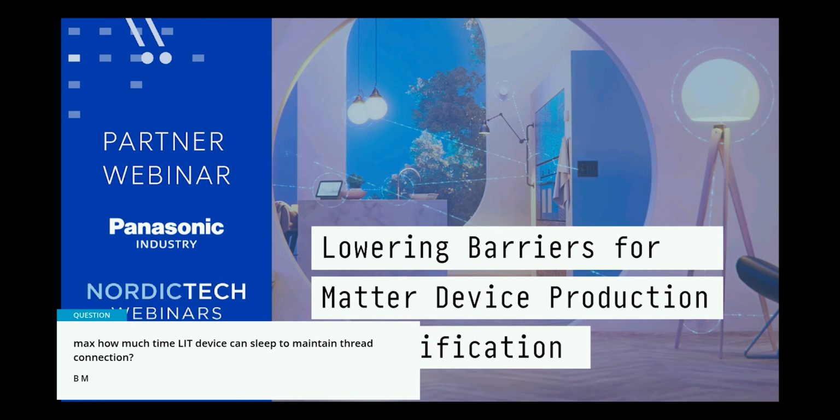How much time can a LIT device sleep to maintain the Thread connection? Generally, by the Matter specification, the maximum sleep time is 18 hours. However, that's the interval on the Matter layer, and to maintain the Thread connection, there are also other parameters like MLE child timeout and child supervision timeout.